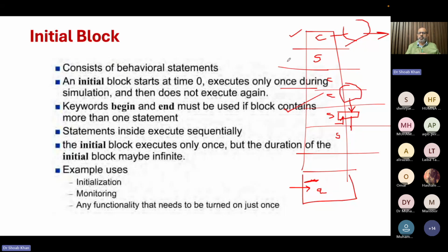So that's why Verilog is so simple to learn. In the Verilog design code, you see nothing else, but if it is a stimulus, you will see a lot of initial blocks. Every block will start with begin and end statements. All blocks start executing at zero simulation time. So you don't know which block will execute when, though they may have been written in a certain order. Sometimes it is mind-boggling to debug the code, because if you have not adhered to very strong coding guidelines, where you make sure only one block assigns to one variable, you will be confused about what is happening.